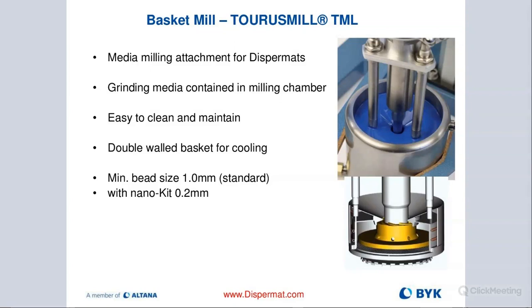There are different designs out there. Our design is such that we purposely don't have a screen or opening on the side of our basket, because we want to make sure that we're cooling the mill base all around. And this is where you would be milling, right in the center of our basket, where all the beads are located. If we have a screen on the side, number one, we can't really cool it properly. But a much bigger problem is the wear on the screen, because this is where all the beads will impact. So you would see very high wear of the basket mill if you have a design like that, where the screen is on the side.